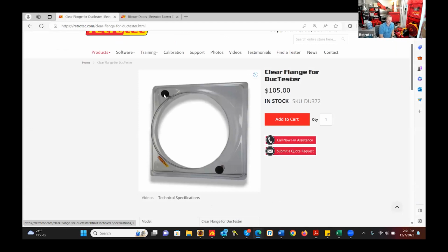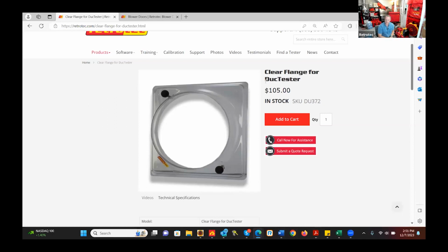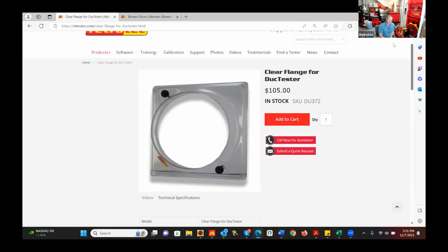There is a similar flange for our commercial duct tester. And that's kind of our best option for connecting to registers. If you're connecting to the air handler unit, unfortunately, we don't have one specific to that. You can use this still. Because those air handlers come in such a variety of sizes, there's not really a good option for an adapter to that. Yeah, most people just make one out of corrugated plastic or foam board. Right. And then just tape to it.